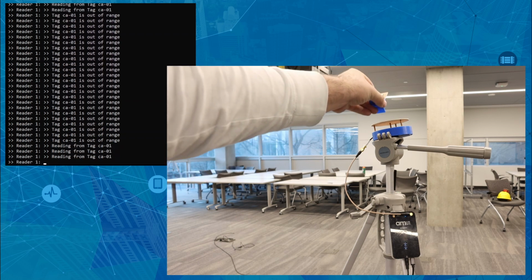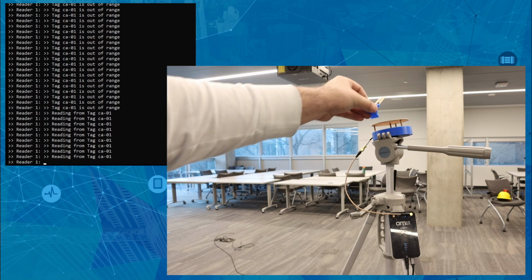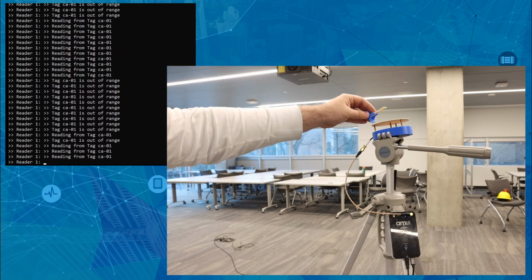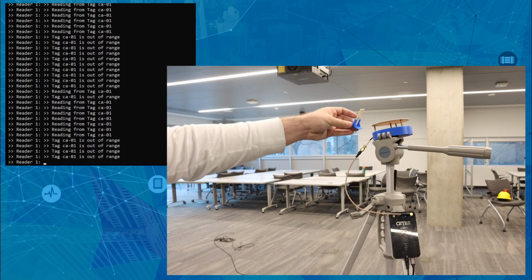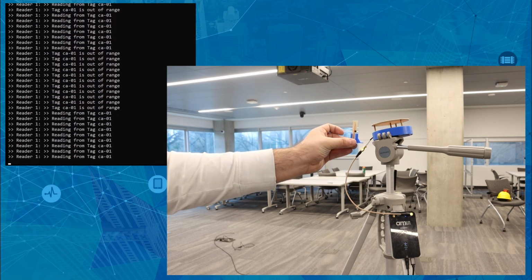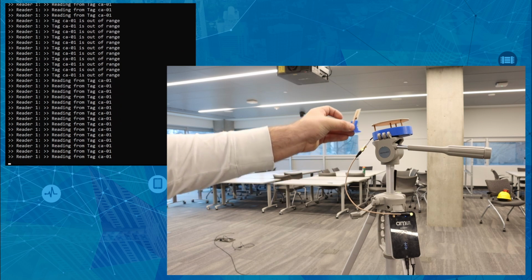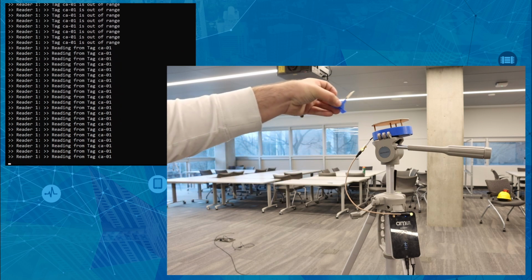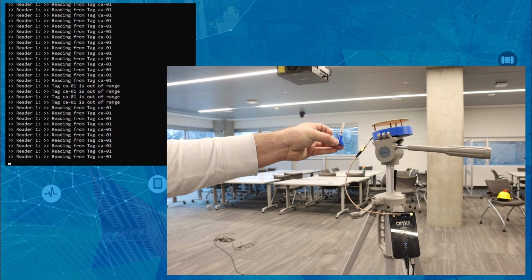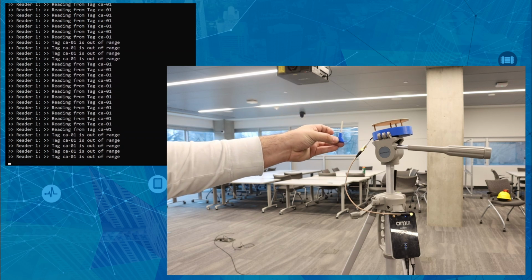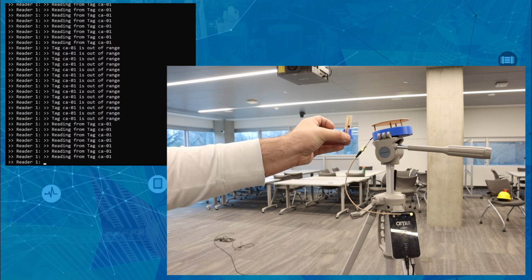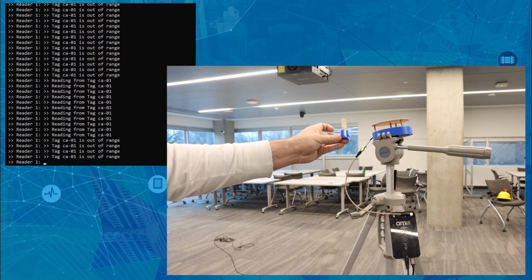The suspected reason for this disparity in performance is poor conjugate matching. While good matching was achieved in full-wave simulation, manufacturing tolerances are large enough such that it is possible for the matching bandwidth to be shifted outside the 915 MHz ISM band. This highlights a disadvantage of narrowband antennas and associated practical challenge with antenna miniaturization. Such antennas may be more sensitive to variation in fabrication than non-miniaturized counterparts. Fortunately, this project is still able to be demonstrated with miniaturized CP antennas.